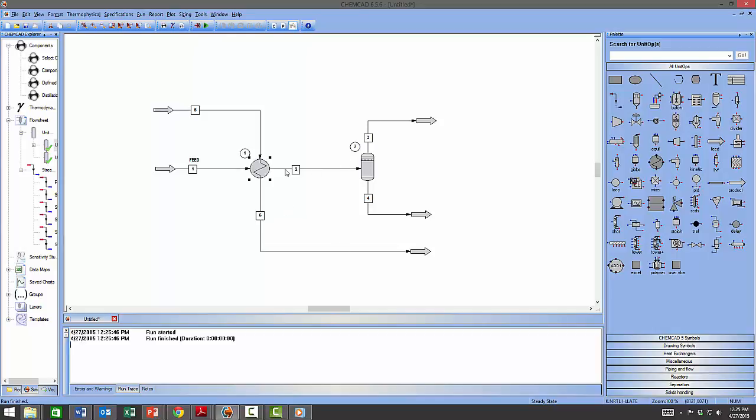And now if you come in here, you will realize the temperature is at our design target, and the flow of stream 5 has now been reevaluated. As you can see, it is now 26,000 kilograms, which is 26 tons per hour. By the increments we were doing, we needed to keep incrementing quite a bit to get to that.